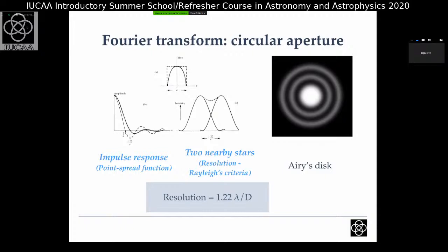So you can see that the width of them can be slightly different, and the side lobes are also of different level. So the choice of aperture, or how I design my antenna or a telescope, crucially depends on what kind of resolution I want and what kind of side lobes are desirable for my experiment. Ideally, we would say, give me a telescope which has almost zero side lobes and has infinite resolution. But of course, in practice, that is not possible. So a lot of trade-offs come into play, and we will consider some of them.